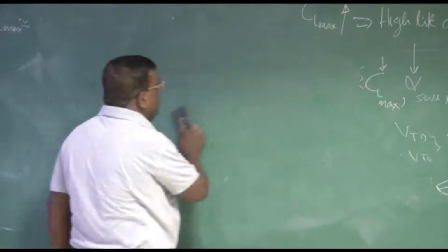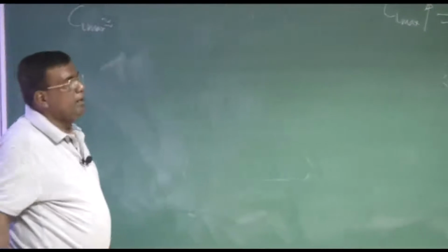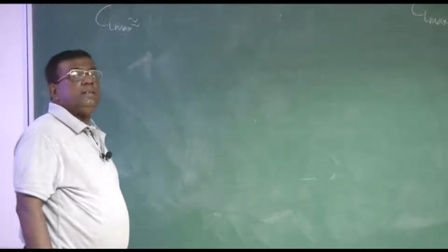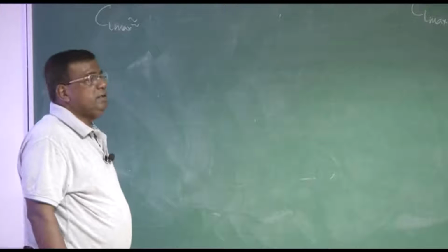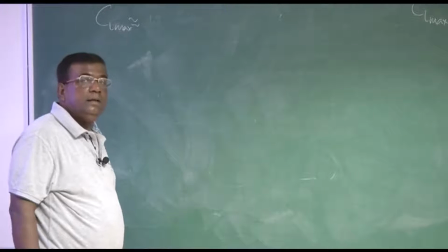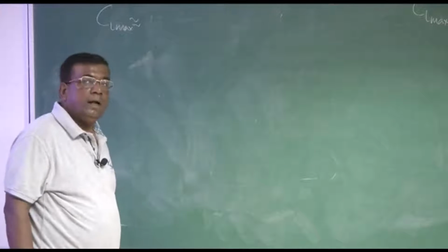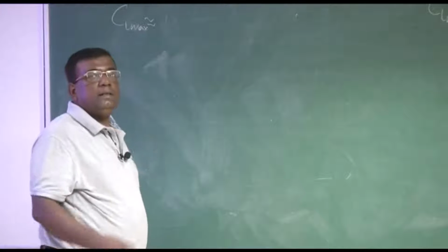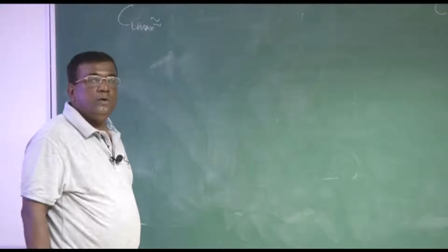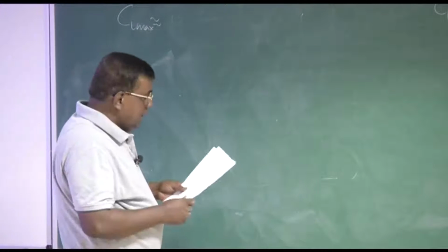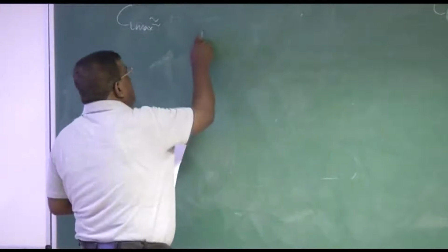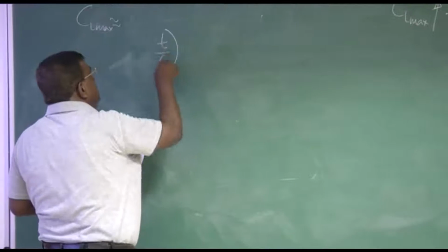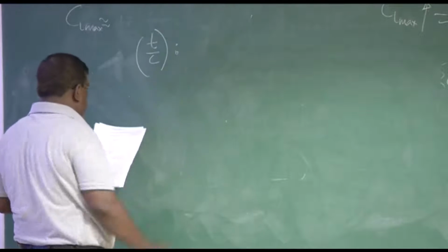At the same time, if you want to make a laminar wing, manufacturing is demanding, as well as keeping that wing clean is also demanding, because small particles may locally turn the flow into a turbulent flow, right? Okay. There's another topic I was discussing, which was T by C, this thickness to chord ratio.